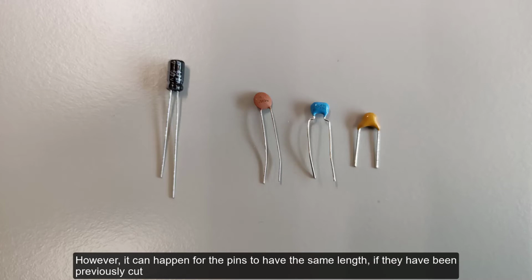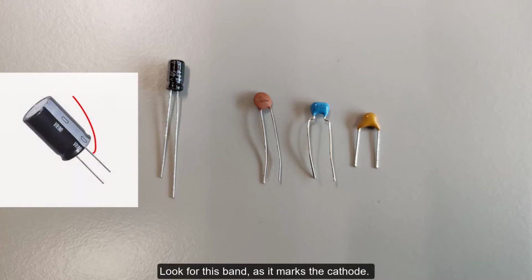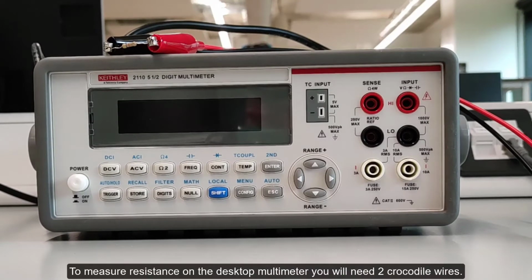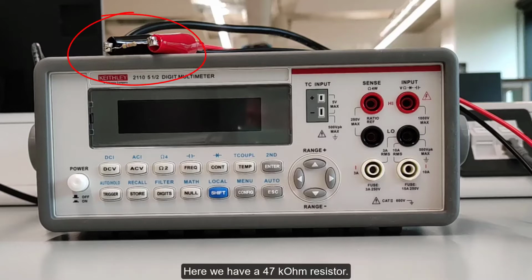However, it can happen for the pins to have the same length if they have been previously cut, so you should always double check. Look for this band as it marks the cathode. You can read resistance and capacitance using the desktop multimeter or by using the RCL meter. To measure resistance on the desktop multimeter, you will need 2 crocodile wires. Here we have a 47 kilo-ohm resistor.